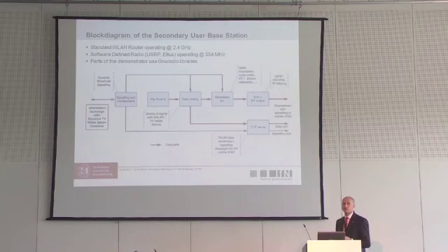And parts of the demonstration include new radio libraries. This is mainly this modulation block, which includes PAM modulation and OFDM and so on. So here is a USRP board from Ettus that transmits at 554 megahertz. This data routing block is connected to a signaling and configuration block, which directly speaks to the dynamic broadcast core network. And here the dynamic TV whitespace database is implemented where spectrum information can be exchanged.